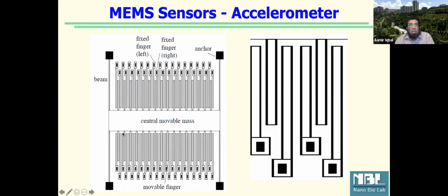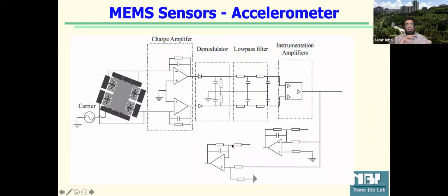When this mass moves, if you go close, in the right hand image, this finger is moving because it is attached to this part. When, say, a car moves too fast in this direction, these things are going to draw a little bit backward because the whole platform is moving faster in that direction, right? Now these two micro beams have a capacitance in between them. If that changes up and down, the capacitance would change, right? Simple concept behind that. It may be an inductor or resistor measurement as well. But that becomes part of a big circuit and we can get an accelerometer chip, right?